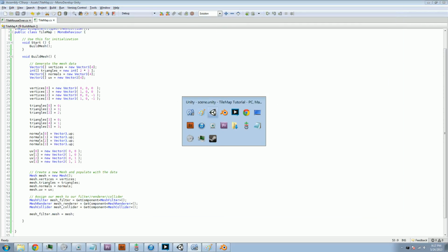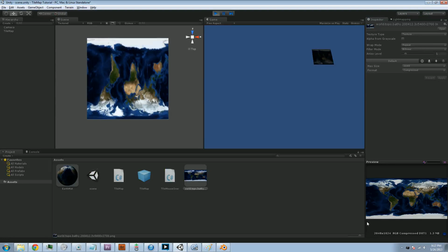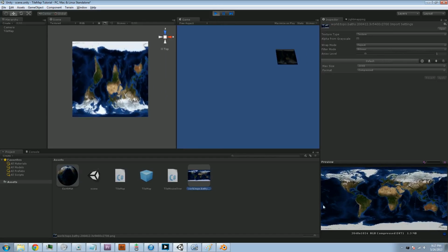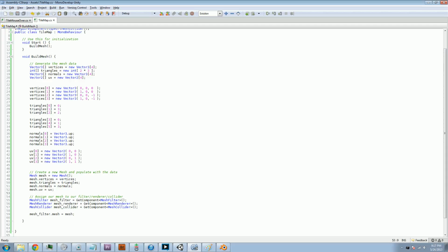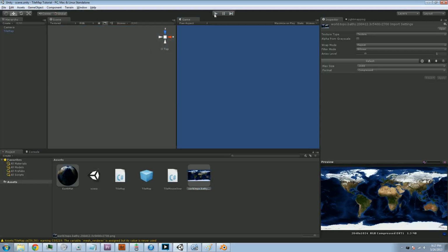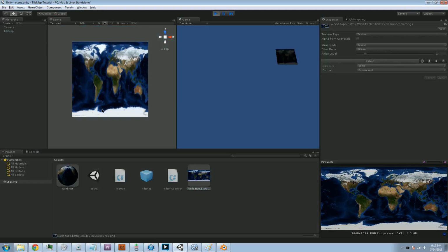The reason is, and this partially depends on what program you're using and a variety of little internal things, for these 2D textures, these 2D bitmaps, Unity actually says that the bottom left is the 0, 0 coordinate. So this is 0, 0. This would be 1, 0. This is 0, 1. And this is 1, 1. So I have to change this around, basically flip these guys around this way. And now if I stop and start, this works there.